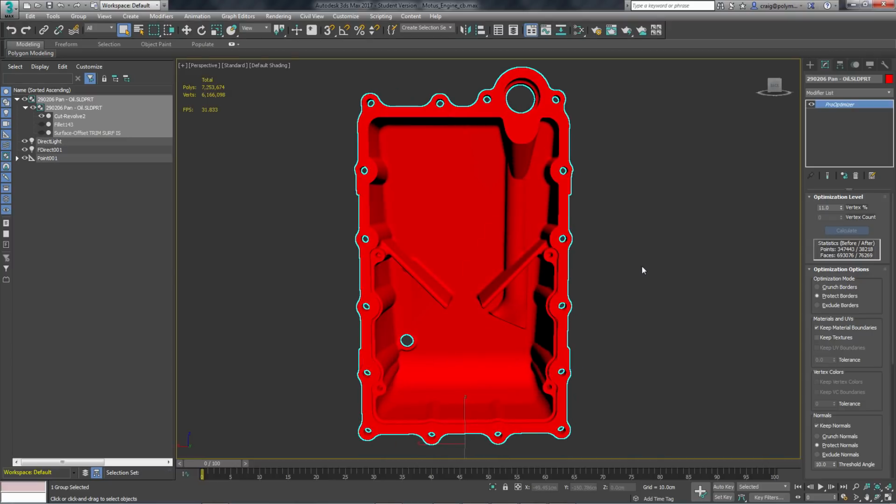Now we need to think about this as one piece versus thousands of pieces. To do this one by one over a lot of pieces, that is something to consider for this conversion process. So batch working with decimation is the way to go. The other challenge here, just the last note on this, is that you want to make sure that you're decimating things in a way that it's preserving that accuracy, but also the parts beside it, the accuracy is there as well. So you do have a bit of a challenge in preserving that accuracy and decimating or lowering things down in a way that actually balances out and represents the CAD design properly.